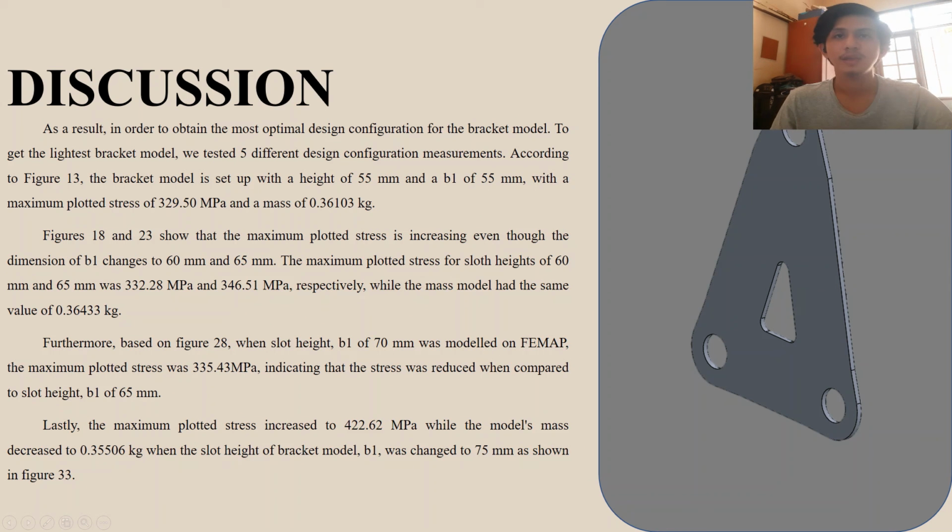As a result, for B1 of 55 mm, we got a maximum plotted stress of 329.5 megapascal and a mass of 0.36103 kilogram. Besides that, the maximum plotted stress increased when the dimension of B1 changed to 60 mm and 65 mm.